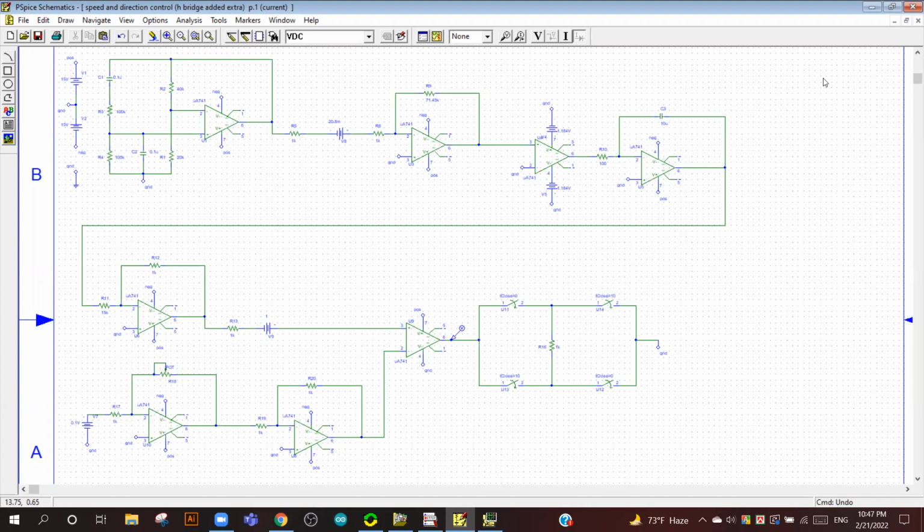The title of our project is DC Motor Control. Our goal here was to implement the learning outcomes from our electronic circuits laboratory for controlling the speed and duration of rotation of a DC motor. Our project is based on the process of pulse width modulation. Here we produce varying duty cycles for controlling the speed of the motor. For a higher duty cycle, we will get a higher speed, and for a lower duty cycle, the motor will rotate at a lower speed. And for controlling the duration of rotation, we have implemented an H-bridge switching circuit.